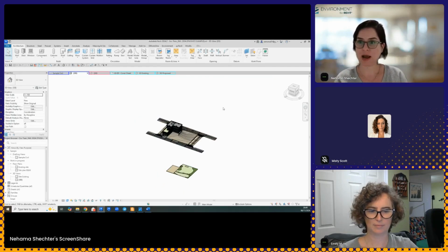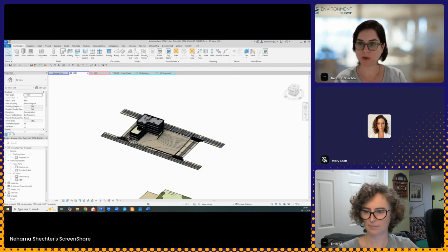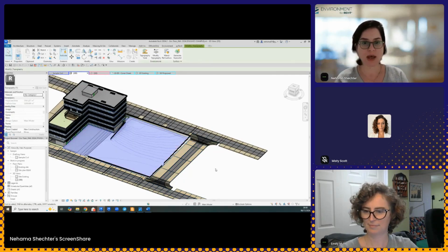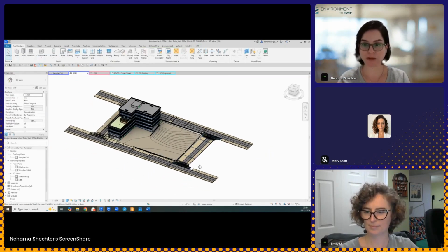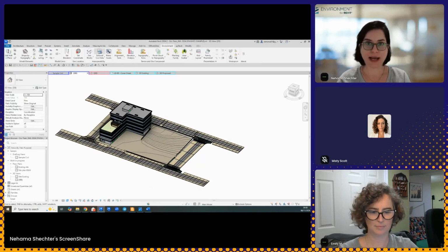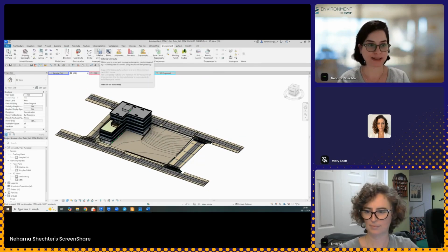And let's go to our Revit model. What I want you to see over here is that these sidewalks and this topography all came from Civil 3D, and they are now live elements within my Revit model. I did that with my external civil data feature.